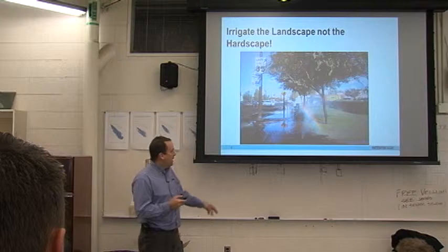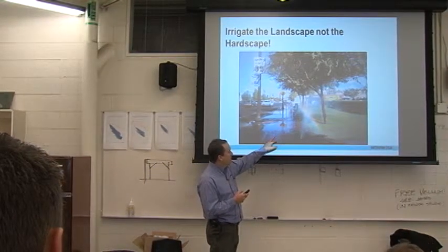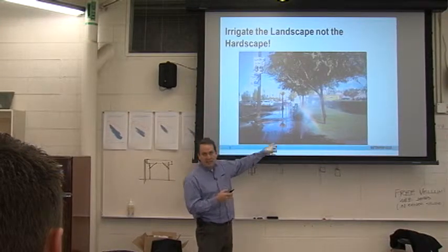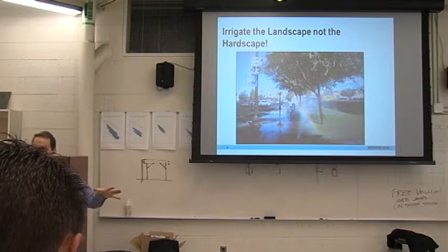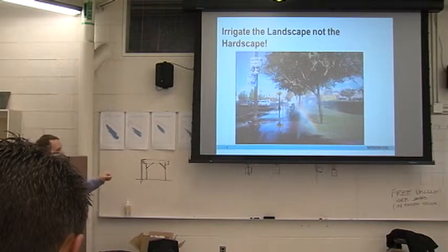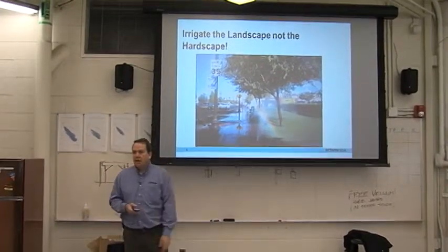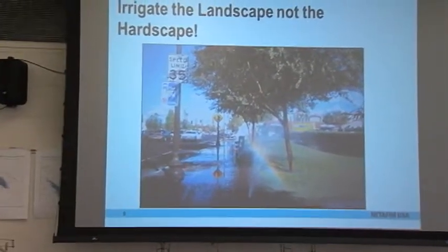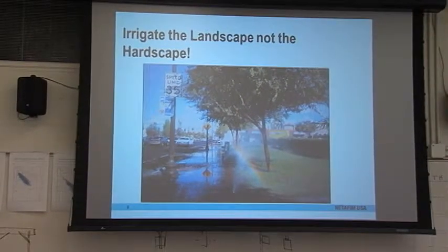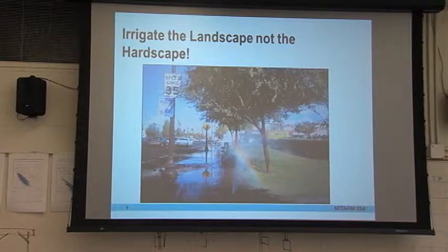And then overhead spray. Here, this is a classic example where we get a lot of wind drift and runoff. This is a brick on sand sidewalk that they paid a lot of money to put in, and because that water is running across that brick on sand, we can start to see a lot of settling going on, some low spots happening in there, and they had to come back in 2 years after this and rip that out and put in concrete. Just great design, but it just didn't fit with what they were doing there. The maintenance of it was painful.